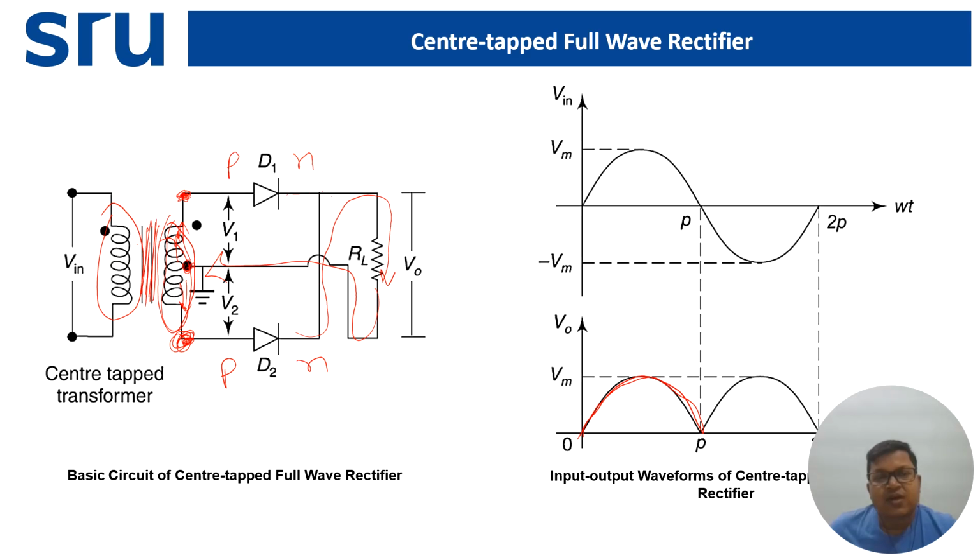Okay, and this position is at a lower potential than this position, that means the P side of diode D2 is connected to the higher potential compared to the N side. That means diode D2 is in forward bias condition, right? And when the forward bias condition is satisfied, diode D2 will be conducting. Similarly, the other path will not be followed in this condition, so diode D1 will be turned off, and this path will be conducting with obviously no voltage drop.